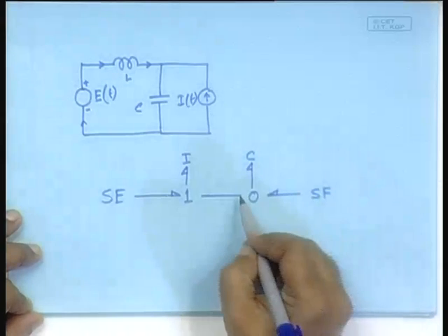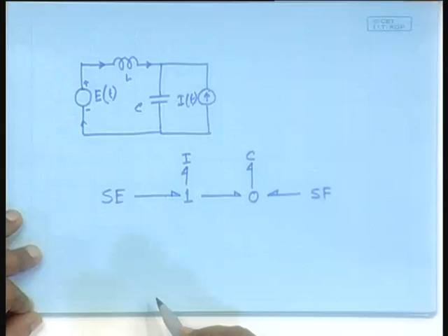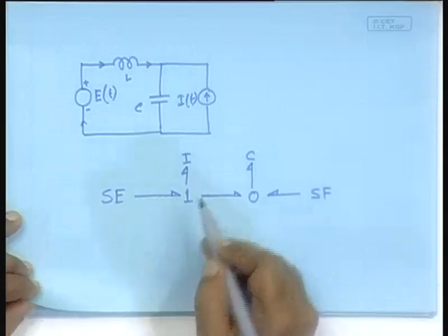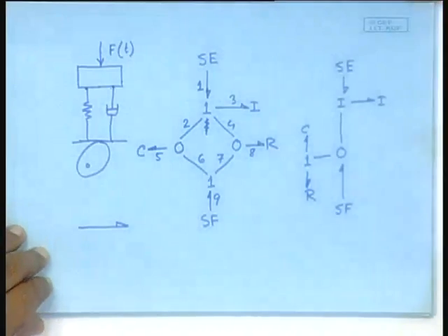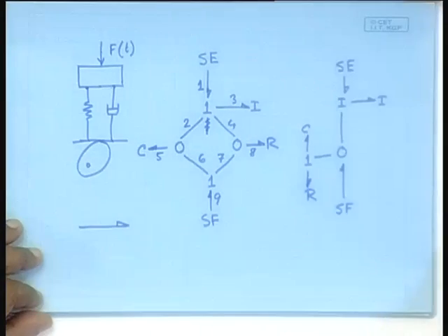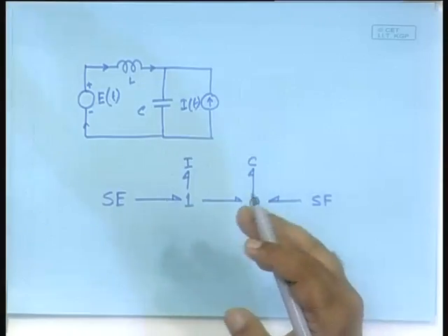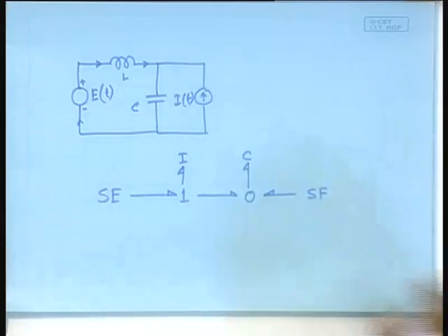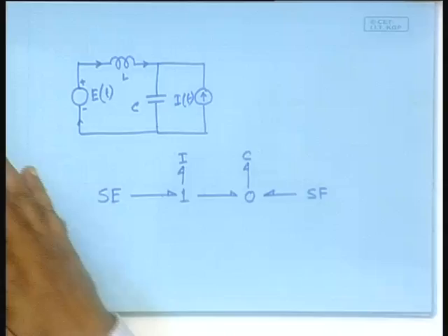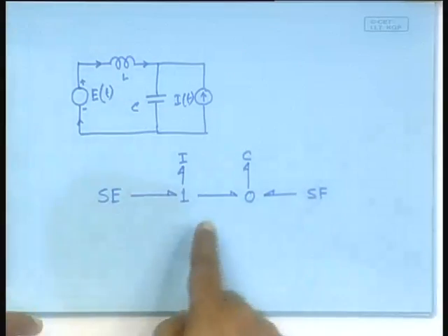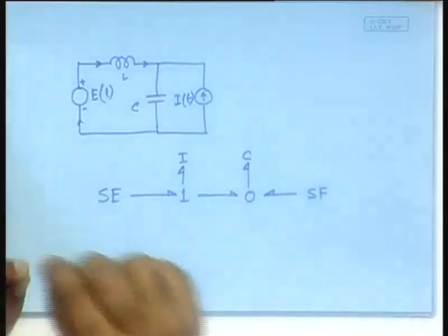There is no harm if you assign it opposite. All that it will mean is that what we call positive or negative will change, but that will matter only when we have already obtained the differential equations, solved them, and found that, say, the capacitor voltage varies like this.